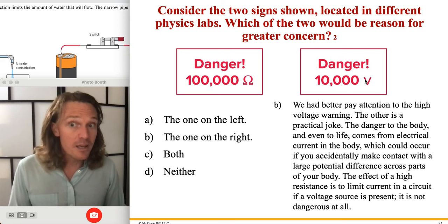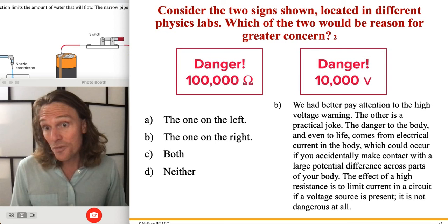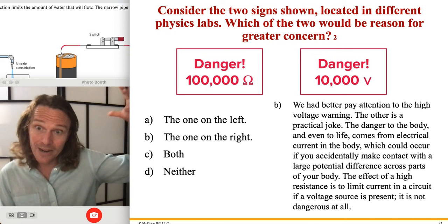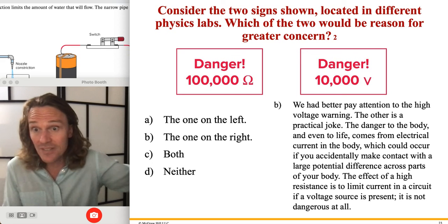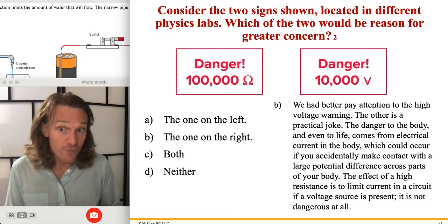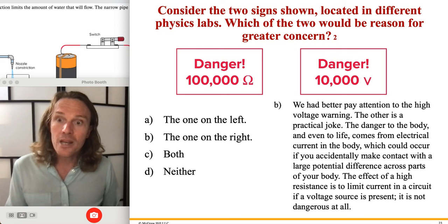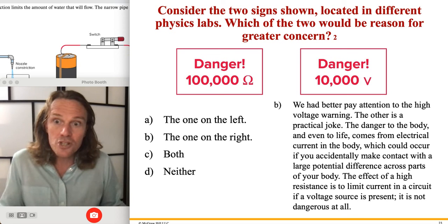But high volts can be. But high volts also can be totally harmless. If you build up static electricity on the surface of a balloon by rubbing it on the carpet, and it has enough static electricity to hold your hair up a little bit, that has tens of thousands of volts, 50, 60,000 volts. But it's not going to cause any harm because there are fairly few charge carriers, right? Still trillions of them, but not like the almost unlimited source that would come out of an outlet. And so once you discharge it, that's it.